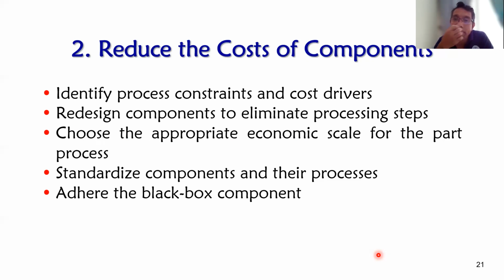So this is very constrained to the production process. For example, the designer may specify a small internal corner radius. For example, they have a part like this. Instead of doing it this way, they make a sample here, like this. So this is radius corners, for example. The designer needs to know why they require this, if it is actually needed, or if they do it without knowing the purpose.